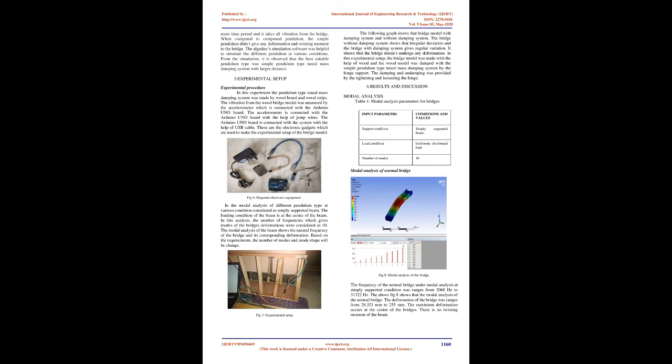6. Results and discussion. Modal analysis. Table 4, modal analysis parameters for bridges. Input parameters. In the modal analysis of different pendulum types at various conditions, the bridge is considered as a simply supported beam. The loading condition of the beam is at the center of the beam. In this analysis, the number of frequencies which give the modes of the bridge's deformations was considered as 10. The modal analysis of the beam shows the natural frequency of the bridge and its corresponding deformation. Based on the requirements, the number of modes and mode shapes can be changed.